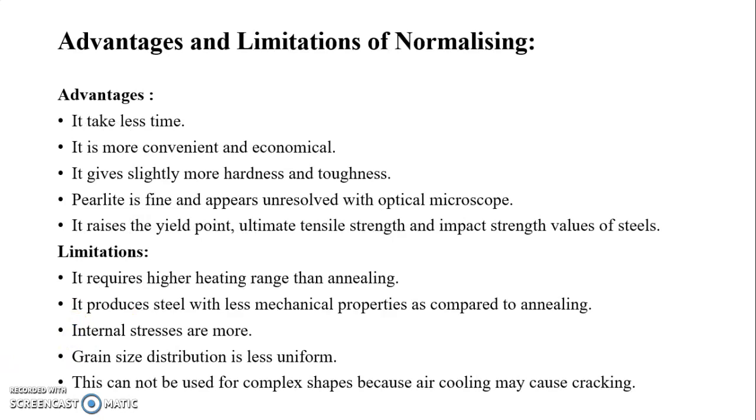First, there are some advantages. It takes less time, and it is more convenient and economical. It gives slightly more hardness and toughness. Pearlite is fine and appears unresolved with an optical microscope. It raises the yield point, ultimate tensile strength and impact strength values of steels.